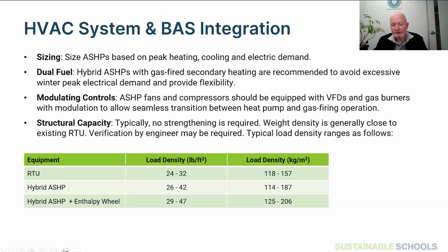And the sizing the units, you've got the peak electrical demand, you've got the peak cooling demand. In the perfect world, they match reasonably well. That the size of the compressor condenser for cooling does a pretty respectable job for the air source heat pump.